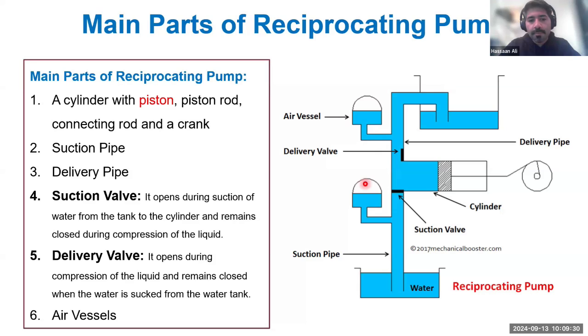Yes. There is a pressure relief valve on top of what we call an air vessel, which, after a certain pressure is built, the PRV will open and discharge air from the top. Yeah. Thank you. It prevents any overpressuring situation. When we go into the examples of these pumps that are used in the oil field, you will see examples of the air vessels with the PRVs.